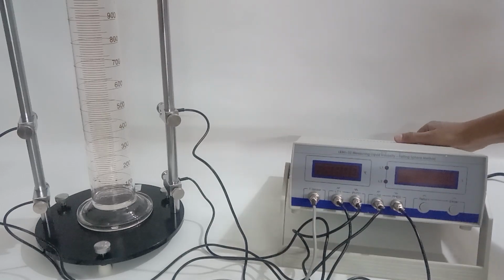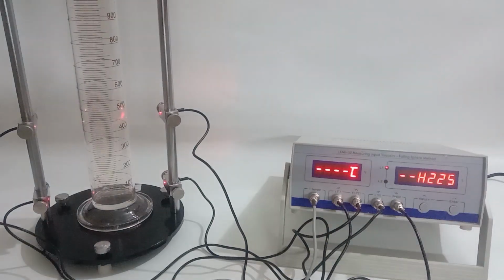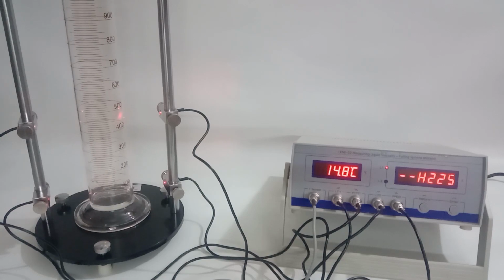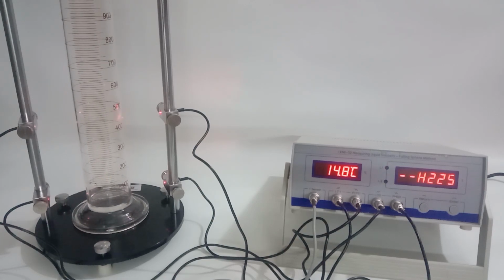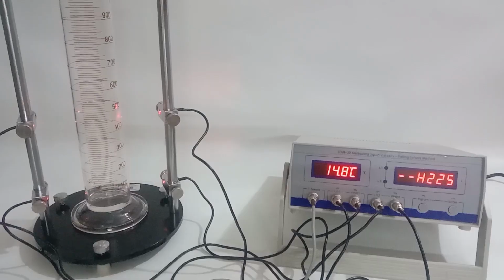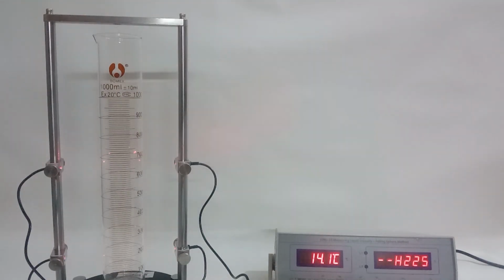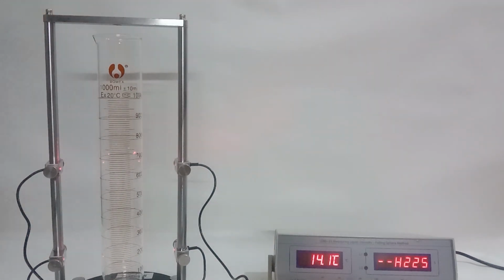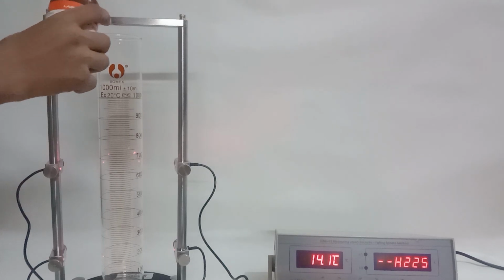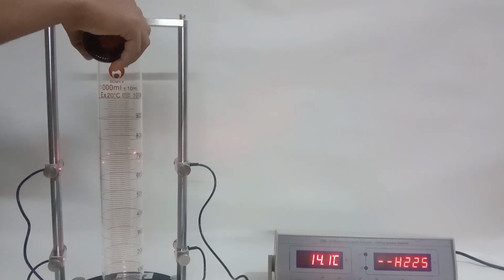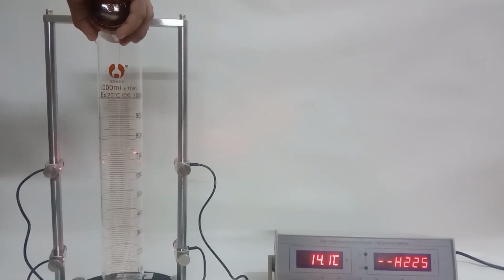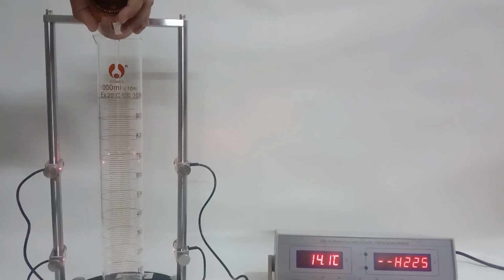Turn this tester unit on, and after turning it on, adjust this cylinder in such a way that both the L1 and L2 indicators go off. After making all the necessary adjustments, you have to pour the liquid into this cylinder, and after pouring the liquid, you have to adjust the falling ball catheter over here. Let's pour the liquid into the cylinder. While pouring the liquid, you have to keep in mind that there should be no bubbles in the liquid.